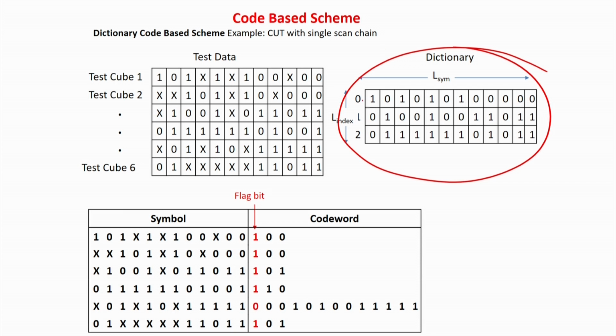Your input is 0 0, 0 1, 1 0, and outputs are this many. Very simple, you can optimize with a 2 variable Karnaugh map. How many outputs will be there? 1 2 3 4 5 6 7 8 9 10 11 12. So 12 Karnaugh maps I have to solve, and I can get a digital circuit. Very simple. The problem is that it is going to be a very large implementation.